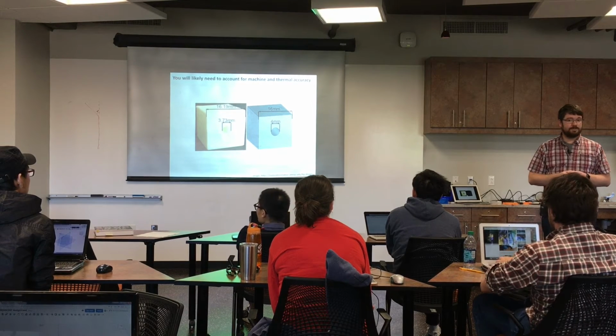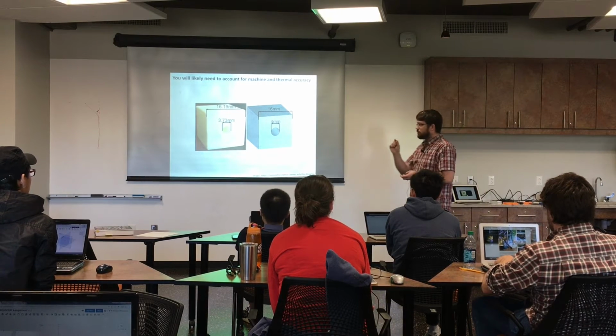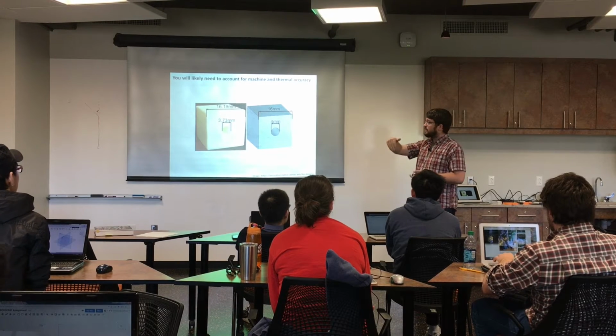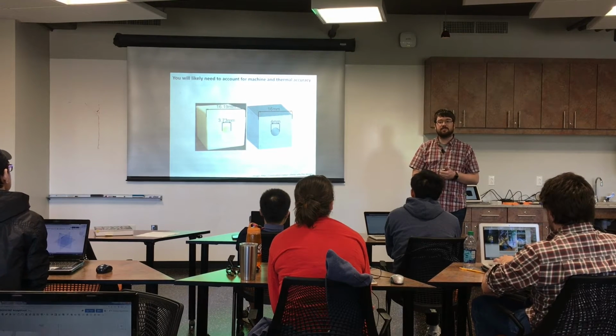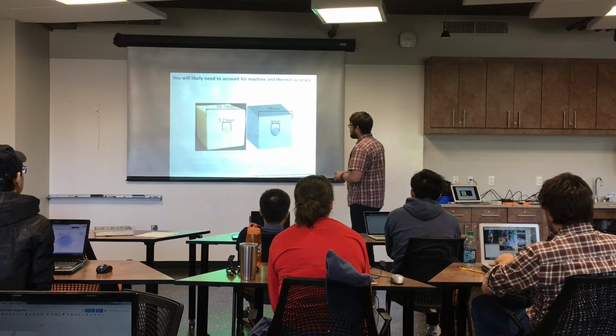dimensional warp to it. So a lot of times people will print parts that have holes of, I want this to be 1, 2, 3, 4, 5, 6, 7, 8 millimeters horizontally and vertically, and then create their own little linear regression for if I want a hole that's this size, I need to put in a hole that's this size into my model because we just don't have that fine-tuned. So it's something to keep in mind.